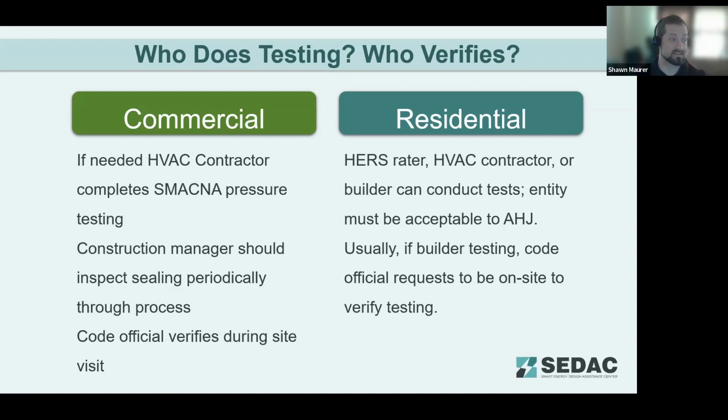As far as duct sealing, both residential and commercial are required to have duct sealing regardless of the pressure level of the ductwork. And so that should be inspected periodically through the installation process of the ductwork to make sure that's being done properly. Usually all your transverse seams need to be sealed. Lateral seams need to be sealed. Joints between collars on ducts should be sealed up properly. And then the code official is going to do kind of a spot check when they come through for their site visit and make sure that all those seams are properly sealed up.